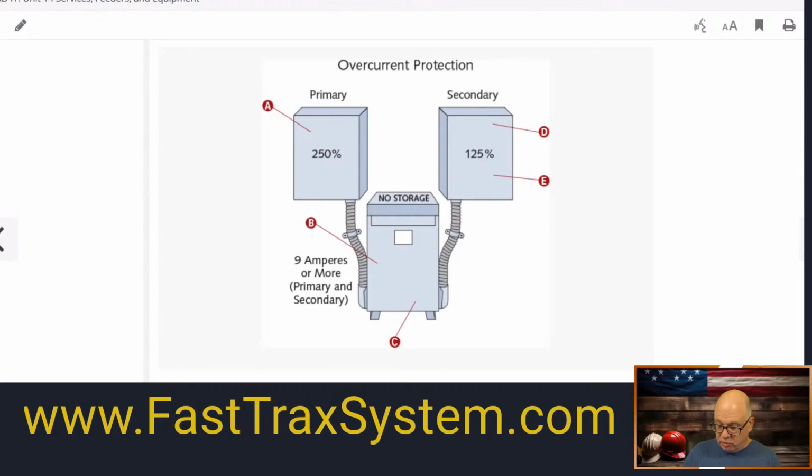So I'm going to go 75,000, and since it is 3-phase, I have to determine 480 times what? 1.732. So I do 480 times 1.732, and that gives me 831.36. Then I take that 75,000 and divide it by 831.36, and that gives me 90.21 amps.